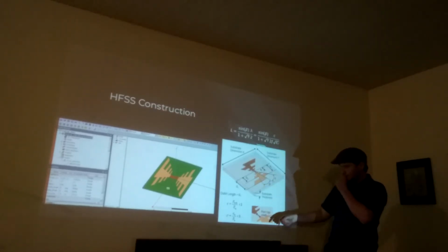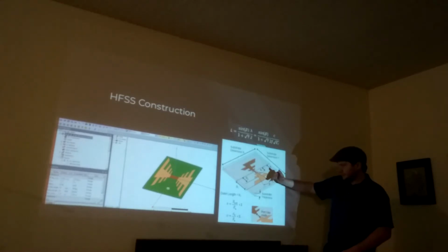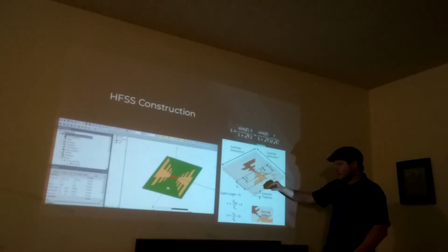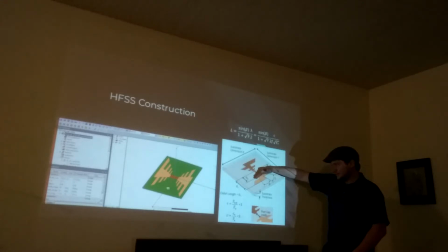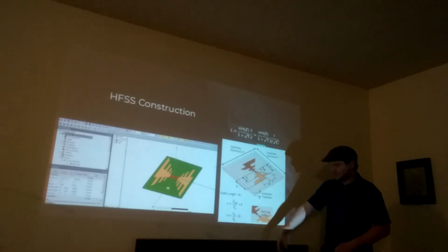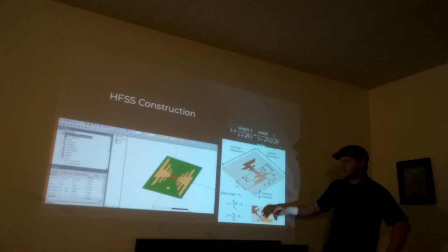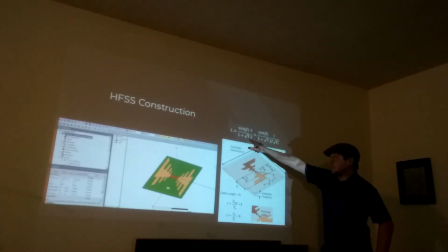Now, a nice thing that you're allowed to choose is sigma, which is the ratio between this length and this length from the origin, and then tau is the ratio from this length to your next tooth on the same side. And what I chose is for those to be the same. So in other words, sigma is equal to the square root of tau. And that's why there's a square root of tau here.